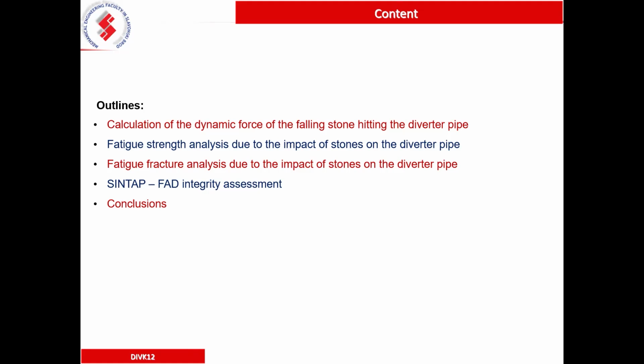So we made fatigue strength analysis and fatigue fracture analysis, and at the end we put our data into the synthetic failure assessment diagram integrity assessment procedure to find the final crack value which would be critical for the pipe.